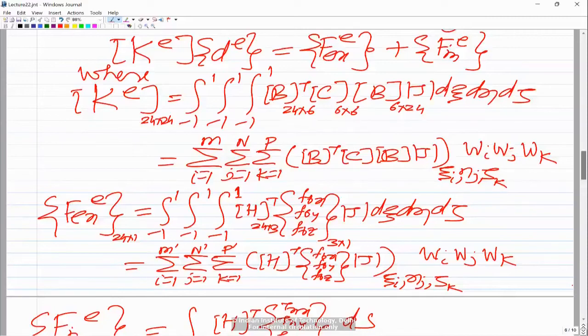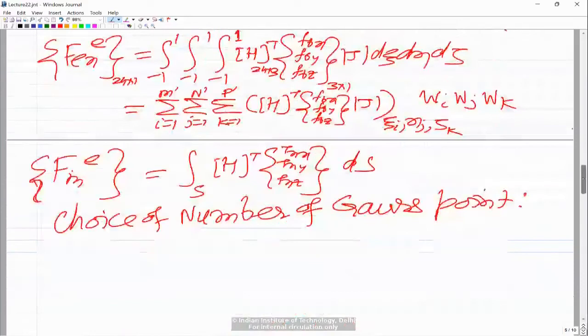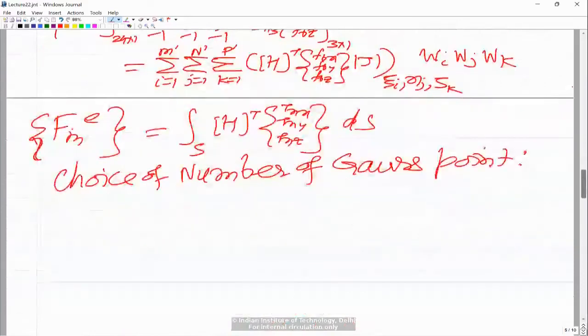So when we take their derivatives, one natural coordinate would go, but the highest power of the other natural coordinates would still remain as 1. So the power of xi, eta, or zeta in B would be 1, and again multiplied by B will be 1 plus 1, 2. So the highest power of xi, eta, or zeta is going to be basically 2.